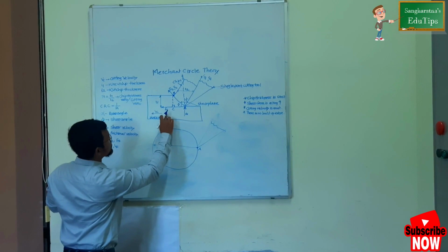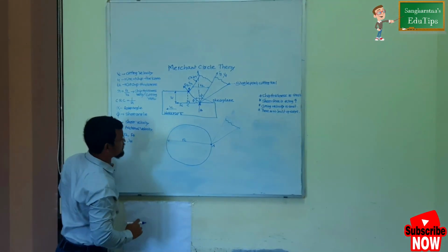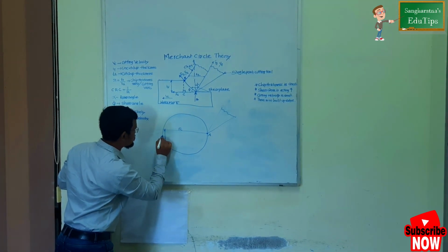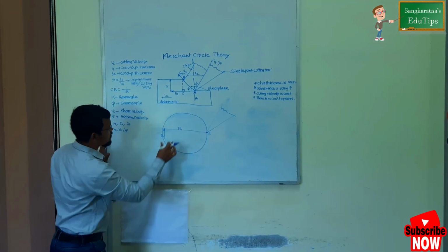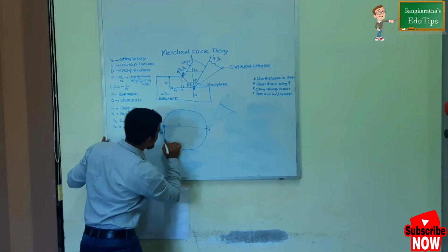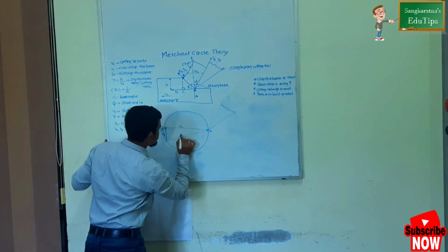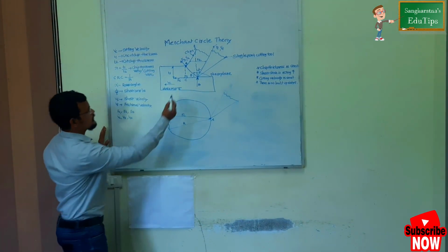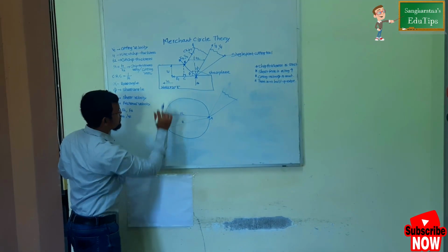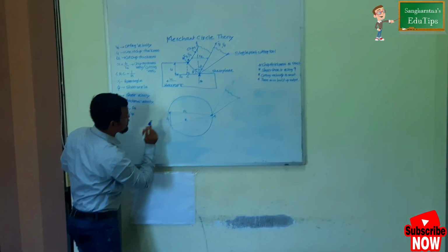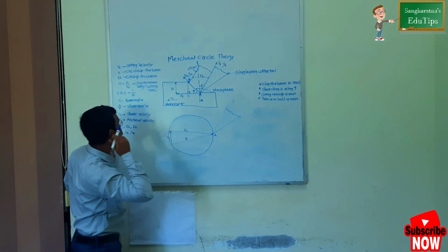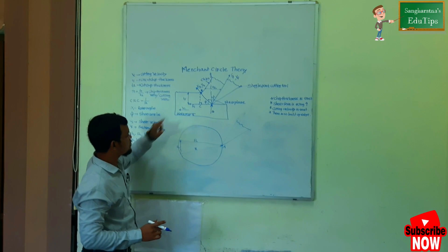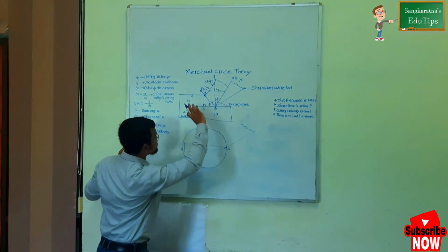We know that perpendicular to this cutting force there will be FT. So we will represent this FT here, right? FC and FT, the resultant will be R, and this R also plays an important role. So in a simple figure, in the horizontal direction there will be FC, and in the vertical direction, perpendicular to the cutting force, there will be FT. Now for this R we have to represent the shear force. As you can see, from A the shear force goes upwards. So simply copy it as it is.